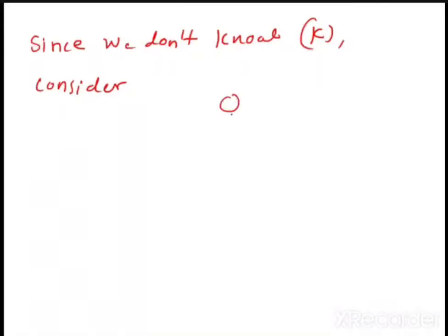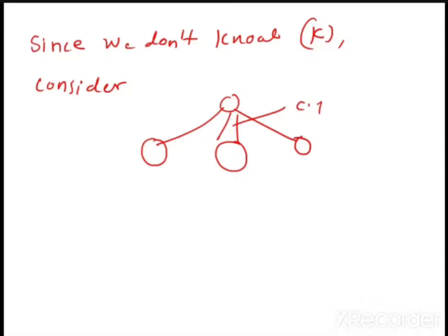If you take this connecting rod like this, you know that this will oscillate from this point to this point. So this connecting rod is nothing but a rigid body. It is oscillating at the point of suspension O, oscillating by angular displacement theta. So vibrations are created, oscillation is done. So this connecting rod is nothing but a compound pendulum. So this connecting rod is one sort of compound pendulum.